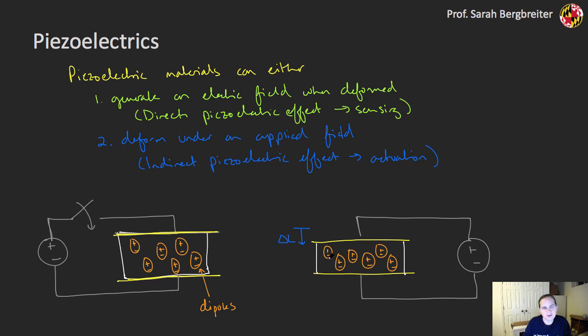So these particular materials, piezoelectrics, can give me a lot of stress. They're typically very limited in strain, even more so than the shape memory alloys. They oftentimes require fairly high fields. There's fairly high voltages applied to them, somewhere on the order of a couple hundred volts. But they're fairly easy to work with. They're just a ceramic. They're not terribly expensive. And so that's why you see them show up in things like the piezo buzzers in the kits that you get with your Arduino.